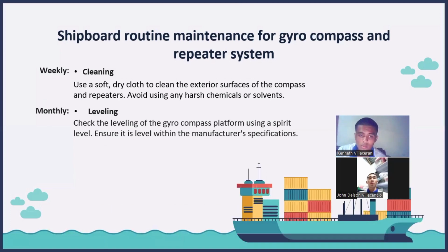Next is weekly. Cleaning: use a soft dry cloth to clean the exterior surface of the compass and repeaters. Avoid using harsh chemicals or solvents.